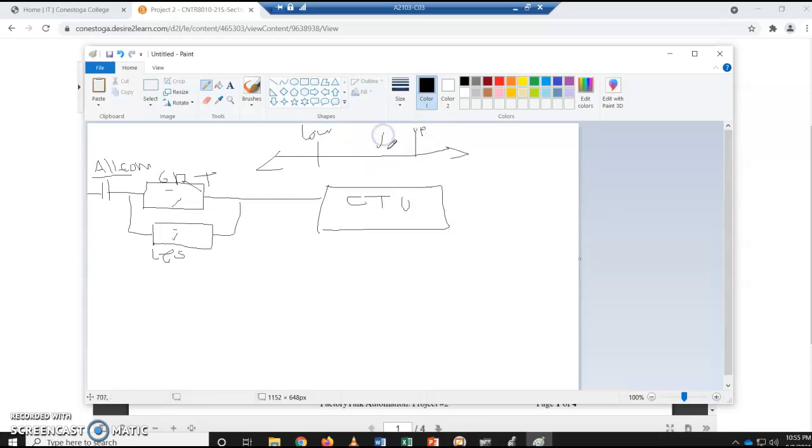If it is between them, it is fine. For fail, it should be greater than up or lower than low. So you should say here, if either of them happened, it is a fault, and this one should count. Remember that this preset should be 5 because it mentioned that if 5 times this happened, do something.